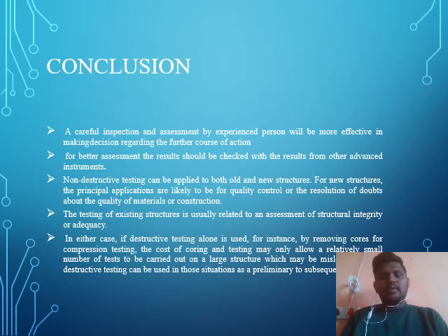The testing of existing structures is usually related to assessment of structural integrity or adequacy, and non-destructive testing can be applied to both old and new structures. For new structures, the principal applications are likely to be for quality control or the resolution of doubts about the quality of materials or construction.